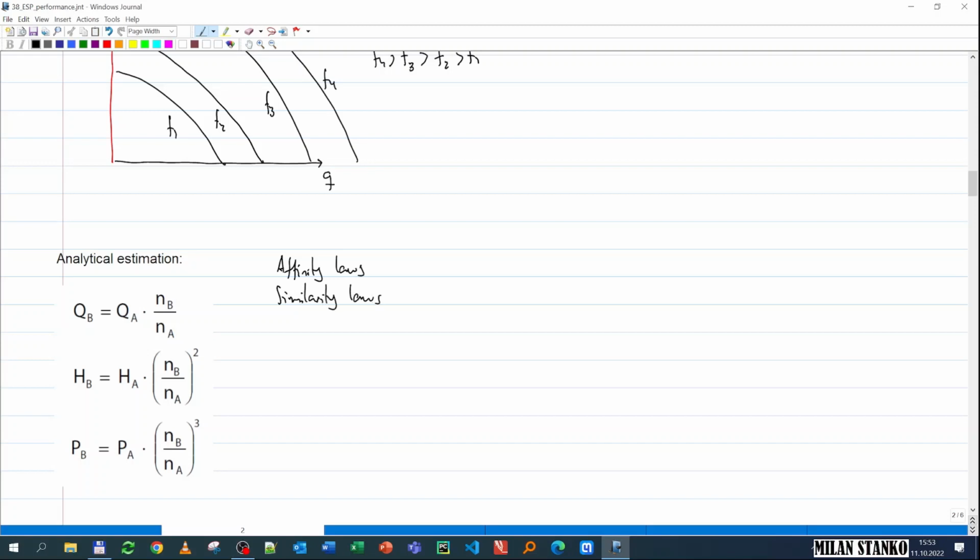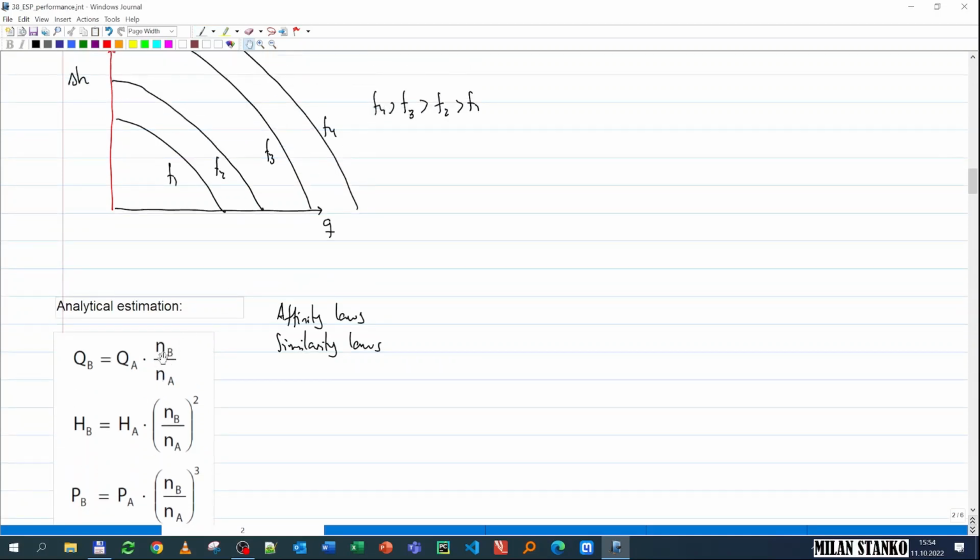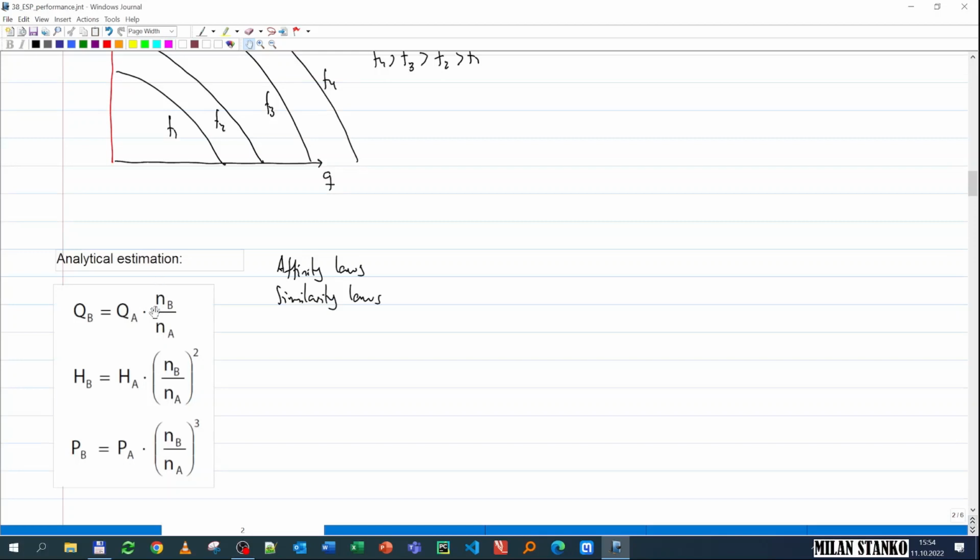And it's a scaling principle. It says that I should scale rate and I should scale head with the frequency. The rate I should scale simply linearly with the frequency. Here the frequency is expressed in terms of N, because they're not using electrical frequency, but a rotational speed, RPM. So people sometimes use N, but it's essentially the same as F. So I scale the rates with the frequency, and I also scale the head with the frequency, but squared.